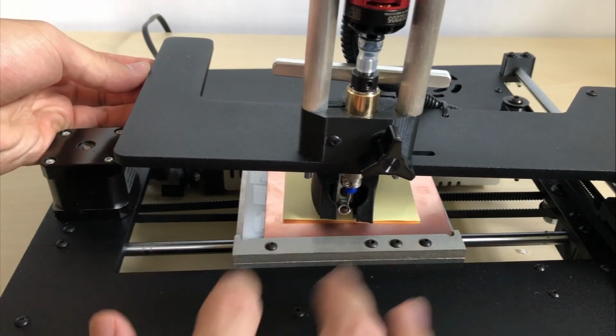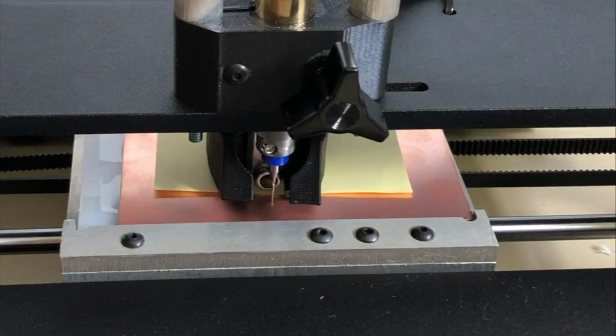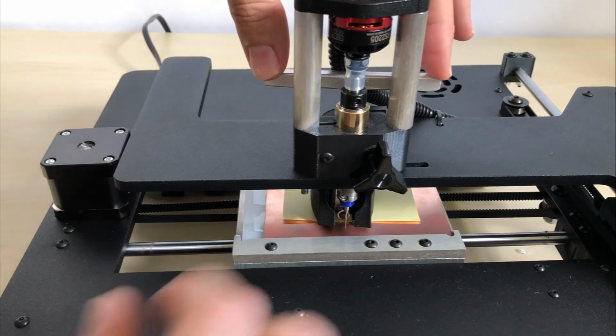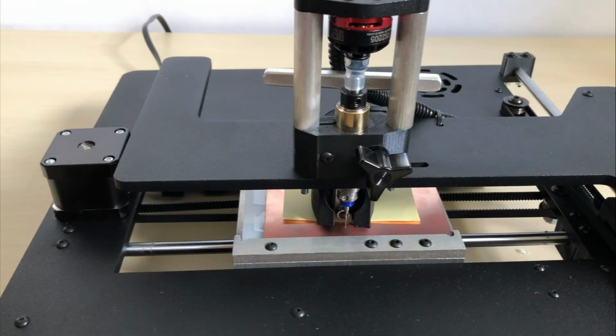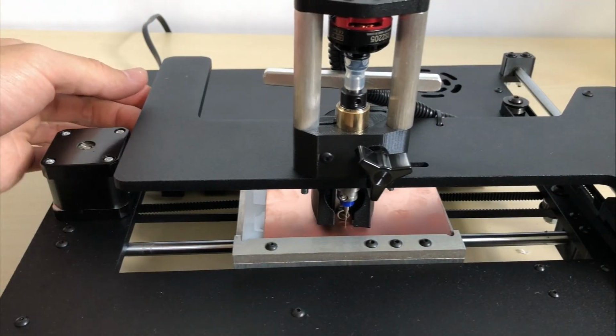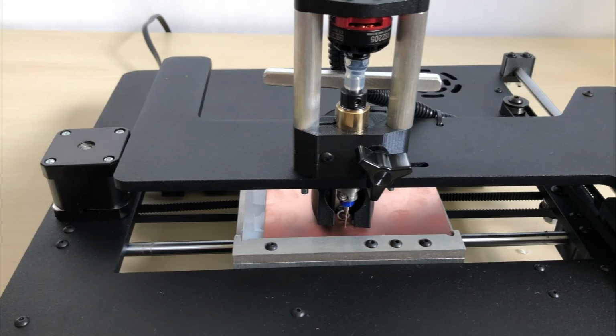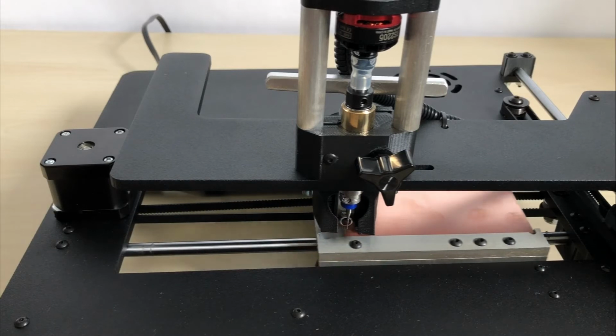Carefully lift the arm and place your paper below the height control post as shown. It is important that the depth control post is on the paper, but the drill bit is resting on the copper board. Once the height control bar is resting properly, tighten the height control knob, and lift the arm to remove the paper. Your drill bit is now set exactly a paper thickness above the copper surface, meaning the cut depth for this print will be equal to the thickness of that paper. Click the Home button in the control panel to return your machine to the home location.